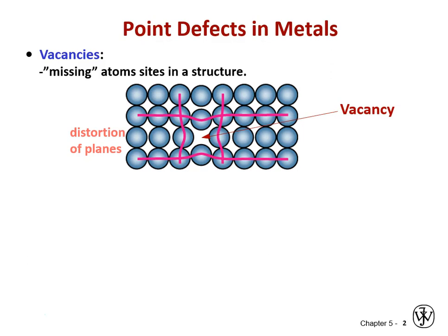If you're not in your equilibrium position, you are at a higher energy, and therefore the crystal is at a higher energy. The more vacancies you have, the more atoms in that crystal that are not at their equilibrium position, the more atoms at a higher energy, the whole crystal is at a higher energy. It's less stable. And this higher energy as a result of not being in the right position relative to that equilibrium spacing is also known as strain energy, and it is a type of mechanical elastic energy. And we can use that to drive processes, actually.